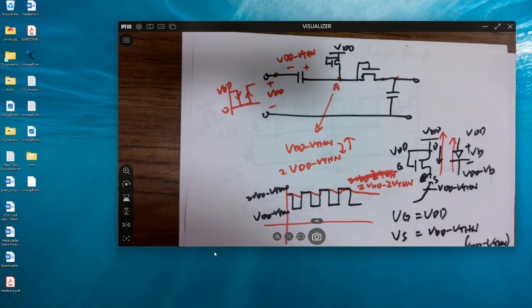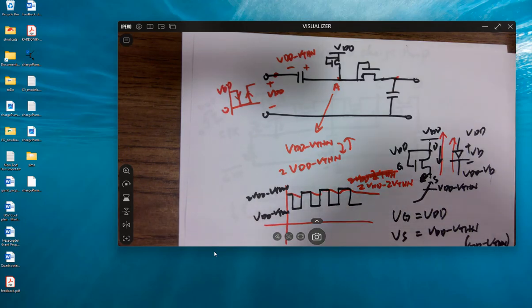It should be fine. I was gonna ask, on just a regular capacitor, how do you tell how much it decays down before it gets charged up again from the pulse? The value, or how much, how you can tell if it's fully charged or discharged. Yeah. If it's fully charged, if you are driving it using a pulse square wave, you should be able to see it stops at certain points and it becomes flat, right? If it's not, it's always oscillating, which means it's not able to drive it efficiently.